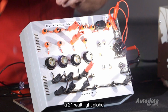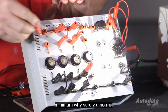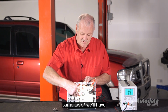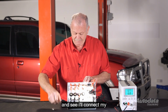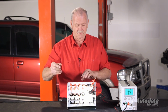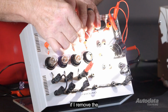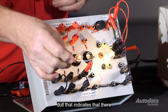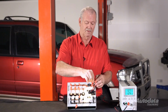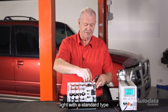I said to use a 21 watt light globe, minimum. Why? Surely a normal test lamp will do the same task. We'll have a look at the difference and see. I'll connect my circuit all back up again. There's our light globe with the short in place. If I remove the short circuit, you can see the light goes dull. That indicates that there is no short circuit. I'll now replace this test light with a standard type test light.